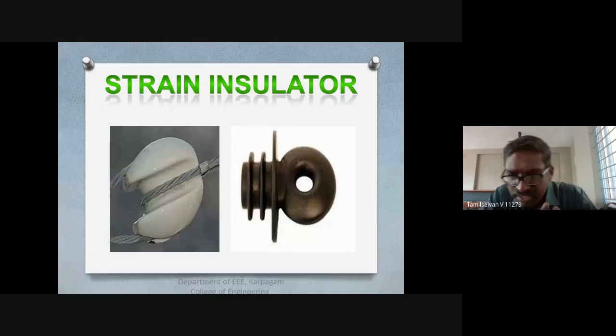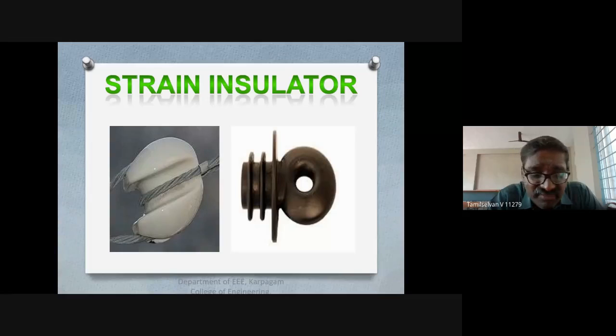So till now, Sumant Reddy, okay. Till now we have seen about insulators. What is the meaning of an insulator? What are the different types of insulators? In that we have seen what a pin insulator is and what a suspension type of insulator is. Insulators are very important in overhead transmission, because we don't need insulators for our underground cables. That is a different type of construction. We'll discuss it after this insulator part, and then we are going to talk about underground cables only.